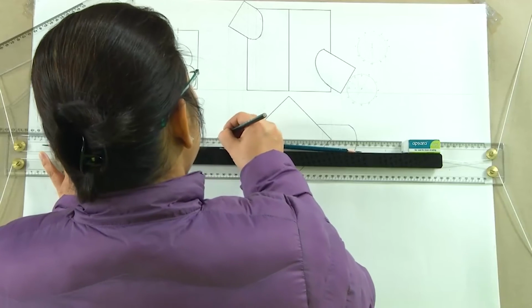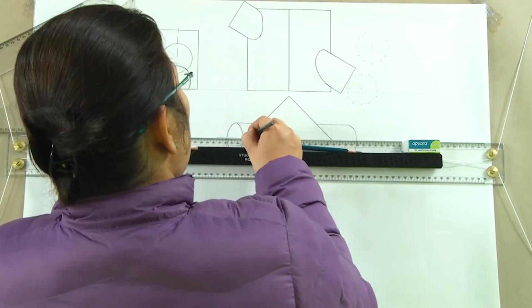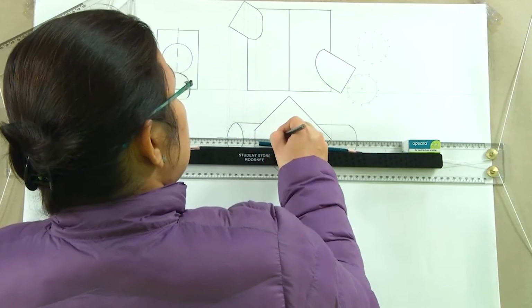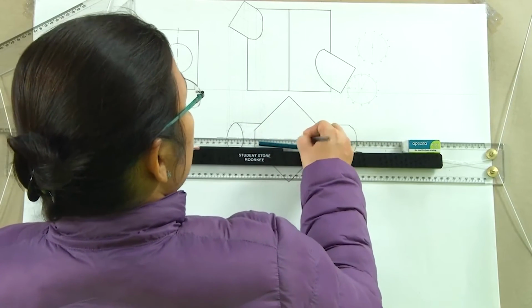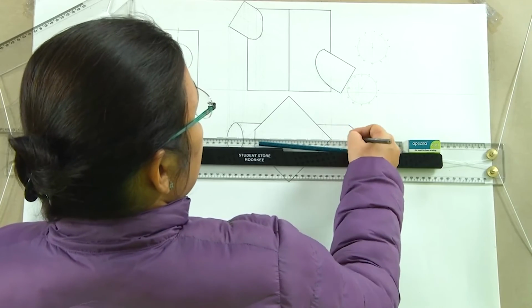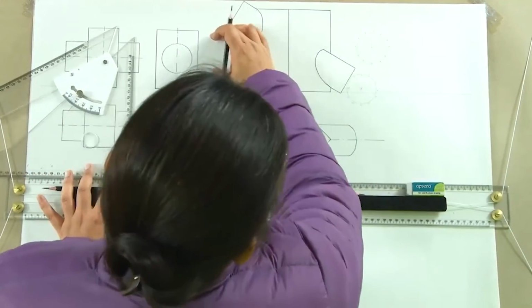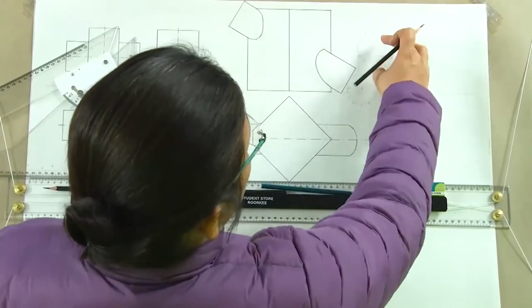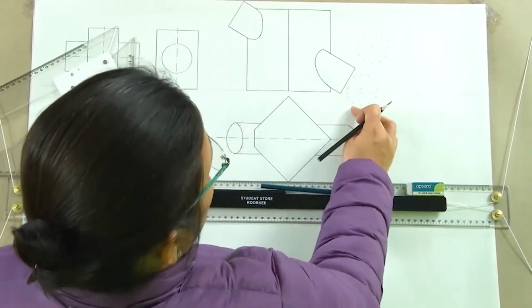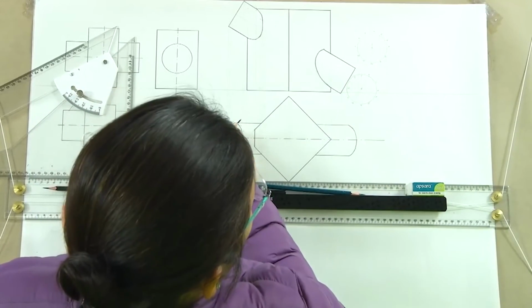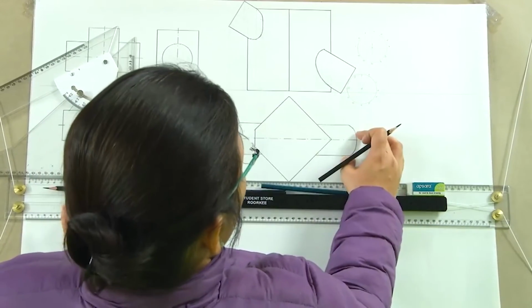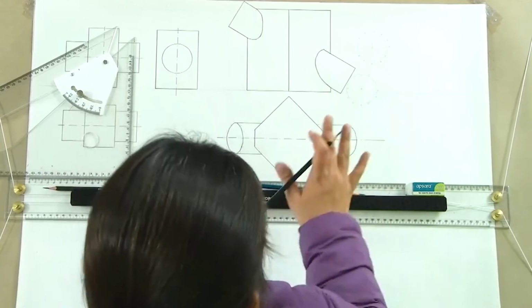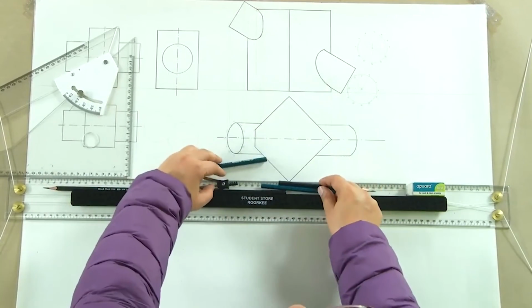So, what we are going to actually do when we are drawing this intersection of surfaces is assume the solid was kept in simple positions, so parallel to both the reference planes or parallel to one and perpendicular to the other. So, which is what we had done, just assuming that it was parallel. Since it was simple, we just had to incline it. We just needed these horizontal projections and then those vertical projections back.